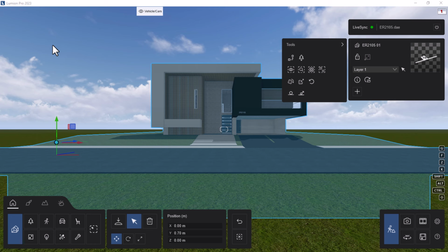What is important here is to know the sequence of your events. In Lumion, I don't know why I keep on saying ArchiCAD. In Lumion, it's very important to time your work, because I would like to do the texturing first before I apply any other secondary 3D objects such as trees, cars, people, stuff like that, just to simplify the model, because it's quite a tough and hardware intensive program.